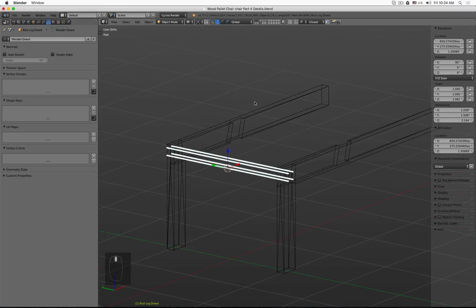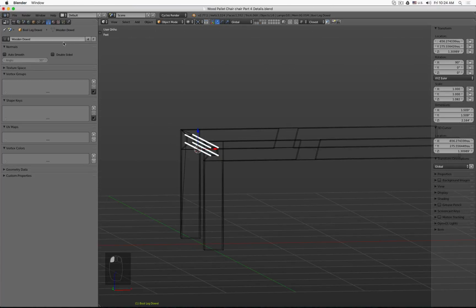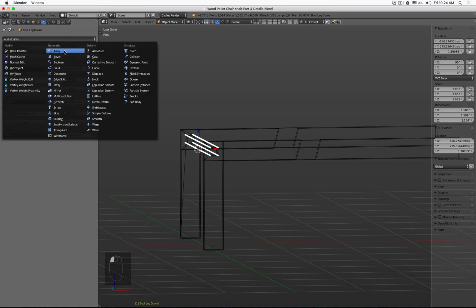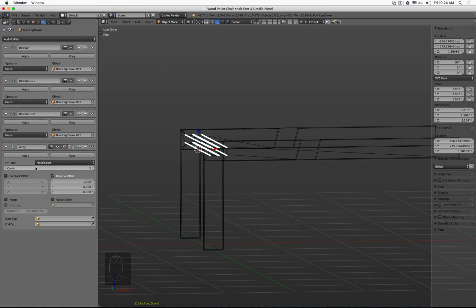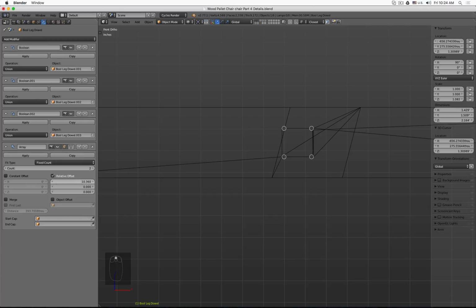So what I have to do in this case is, there are two options we have. For example, we select the object which has the other modifiers. So that includes all the wooden dowels. And then we can give it an array. And for example, say, hey, you array 2 and move this one over. And we just have to try to find a good position for it. Let's say like there. Great.